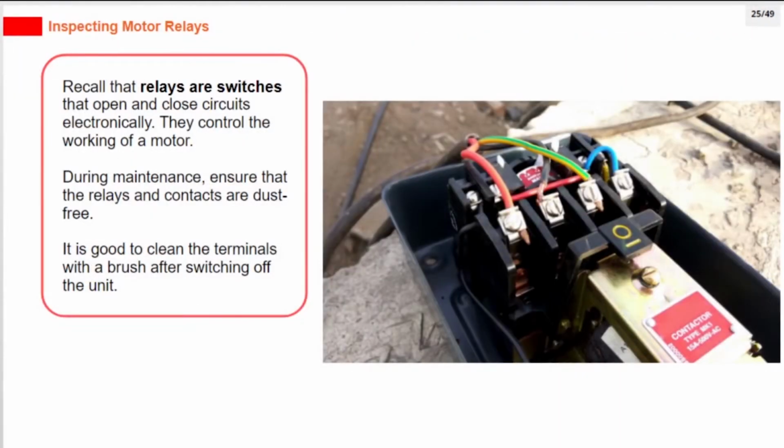Recall that relays are switches that open and close circuits electronically. They control the working of a motor. During maintenance, ensure that the relays and contacts are dust-free. It is good to clean the terminals with a brush after switching off the unit.